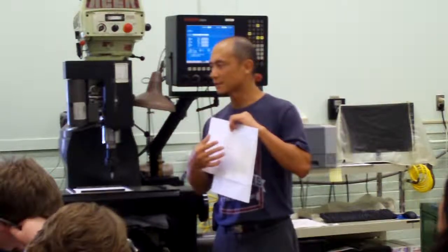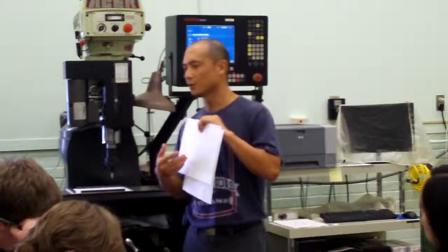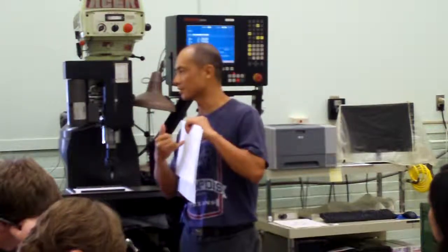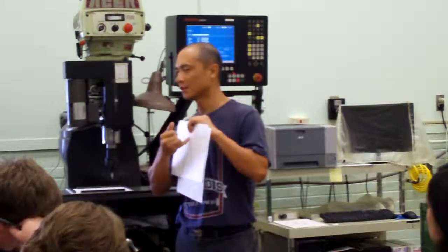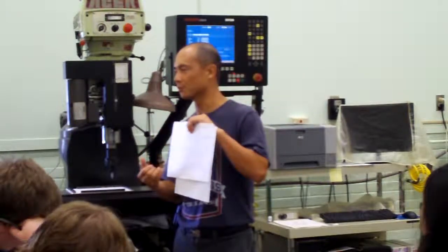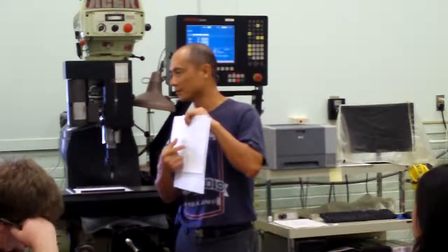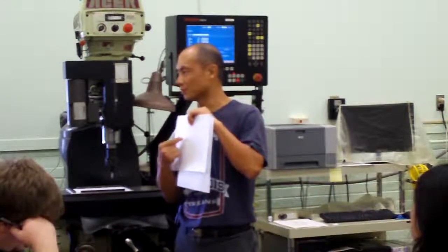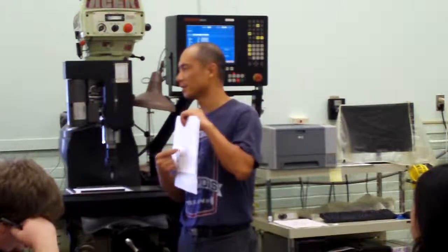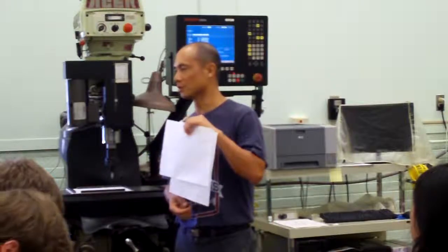So that's the occasion where, if you don't want to or don't care to calculate the coordinates for all these 4 vertices of the window, this is a convenient way to do the drawing, because we know the length, but we don't want to use the length to calculate the coordinates. Then you can simply use the information of the length and the height to do the drawing.